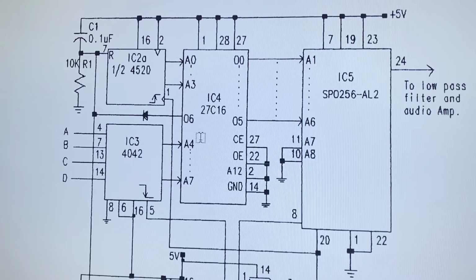So when A4 on the latch, as I said before, is 0, you can scan locations from 0 to 15. When A4 is 1, you can scan locations from 16 to 31. Now, in another case, if A5 is equal to 1 and A4 is equal to 0, now look at the binary weights. A0 through A3 is 1, 2, 4, 8. This one is 16, 32, 64, 128.